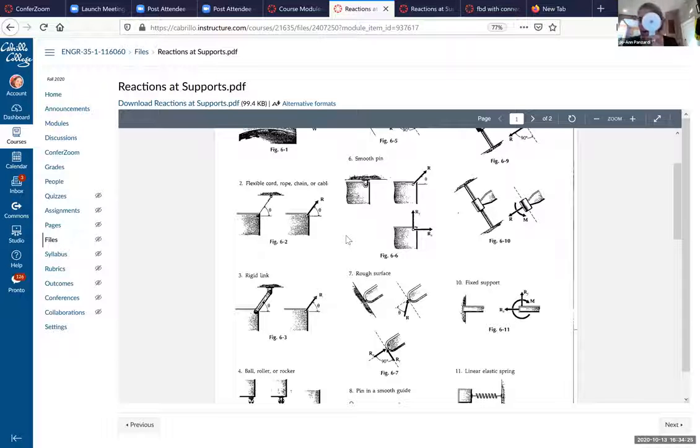Okay, how about Angel? What other kind of motion can this pulley and this rod have in relationship to each other that the pin might be preventing, since it's 2D? There could be some sort of translational motion in the x. Yeah. And there could be a translational motion in the y. So there are 3 different types of motion that a 2-dimensional connection can withstand: a translational motion, a force in the x, a translational motion in the y, and a rotational motion about the z.